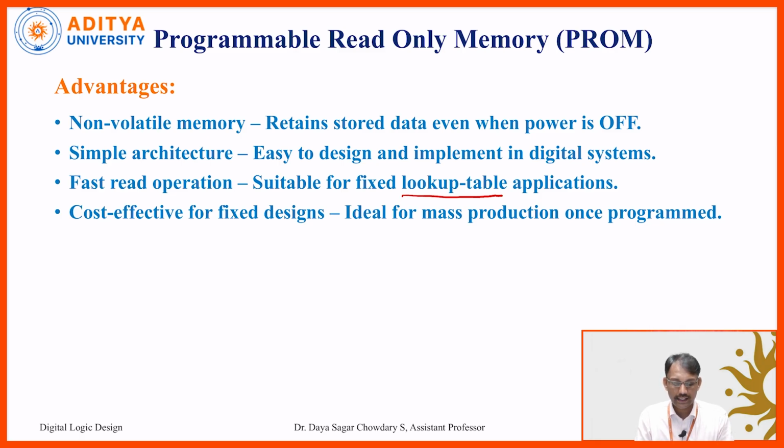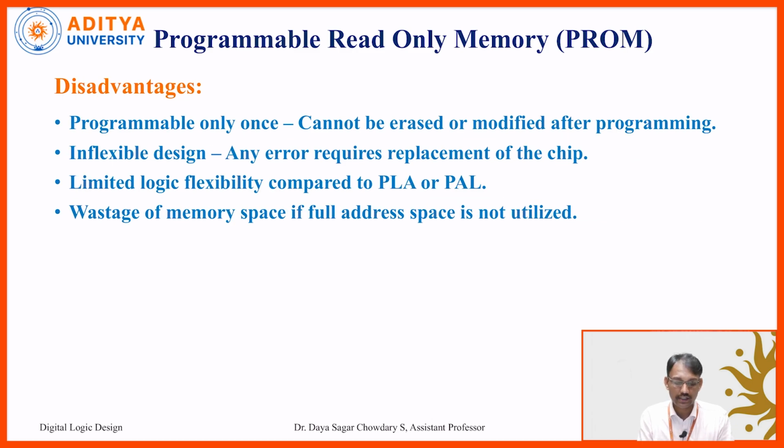And one more thing, this is a programmable read-only memory. The only thing is we can program this device once at a time. That is an advantage. At the same time, that is a disadvantage also. So coming to the disadvantages, what we observed is that it is programmable only once. That means it cannot be erased or modified after programming. So a user can program at once in the lifetime of the PROM.